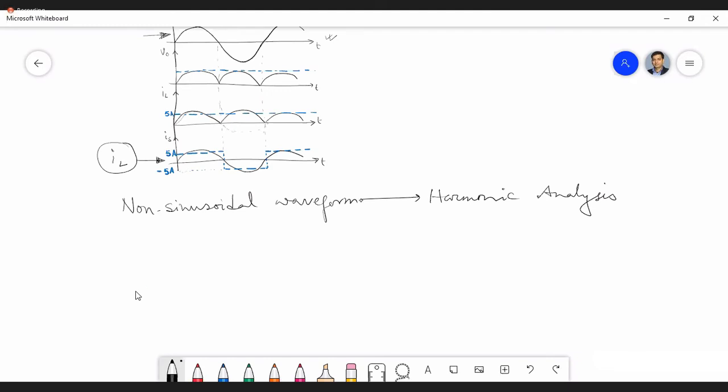We can use eigenvalues and eigenvectors in mathematics, it will be very easy. No, sir, phasor analysis can be done only through sinusoidal waveforms. Because most of the machines are designed for pure sinusoidal waveforms. So if there are harmonics, then there will be humming noise, and the RMS value of the waveform may also increase. So there can be increased heating, which may damage the insulation.